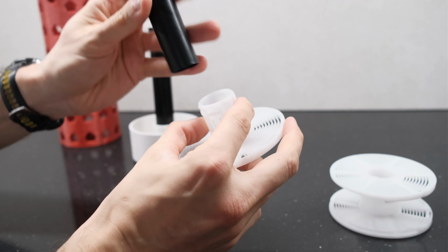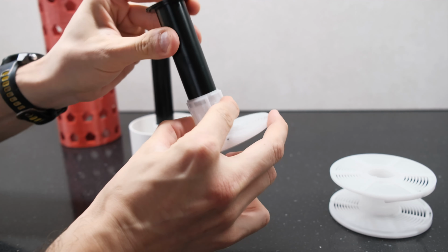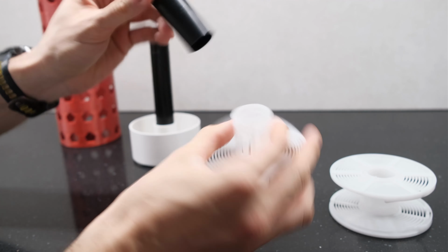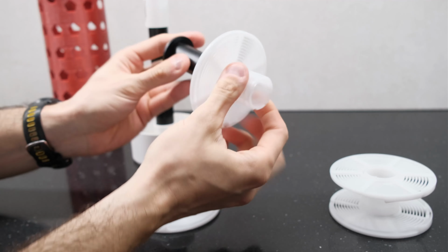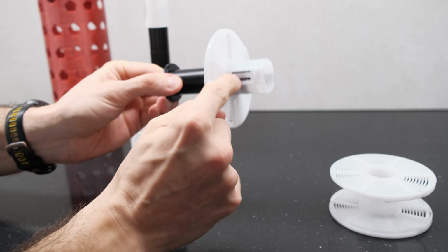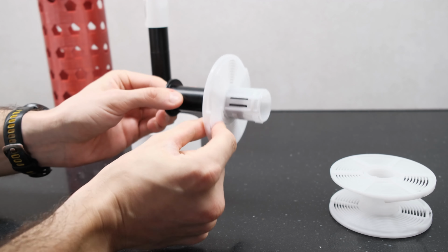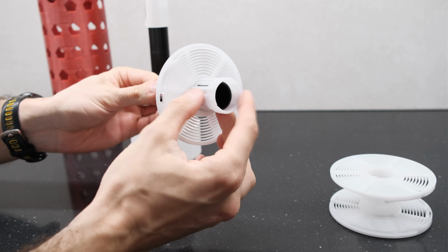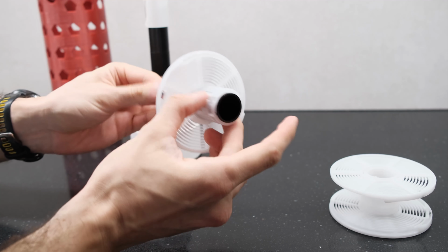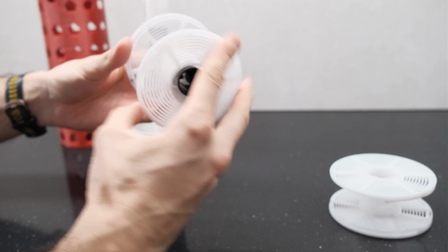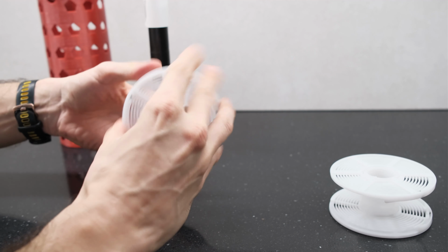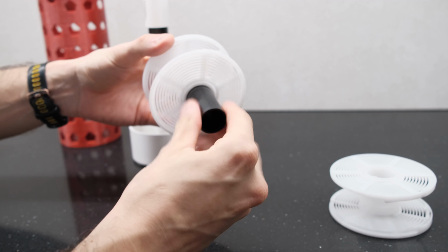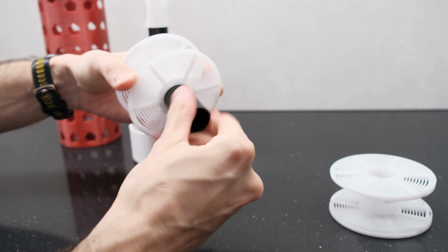But in general, you have a tolerance gap. So you have a gap and your stem goes freely inside this diameter. But at some point, you can see here that the pin has tension and pushes the rod against the wall. This is a kind of spring action provided by this part, and it gives you reliable and good rotation of the part, so it doesn't really go anywhere. As you can see, it's quite snug and a really good fit.